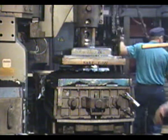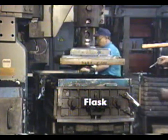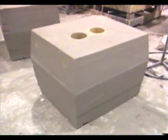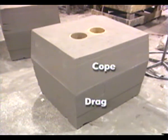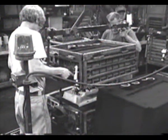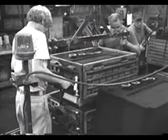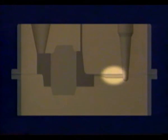Sand molds, made in halves, are built by tightly packing the sand around the pattern in a flask. The upper mold half is called the cope, and the lower half the drag. The mold includes one or more risers, venting provisions, and a system for transferring the molten metal to the mold cavity. This system includes a pouring basin, sprue, runner system, and one or more gates.